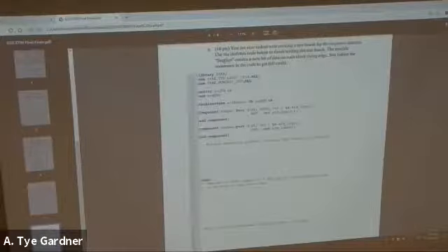Okay. So the first thing that it says to do is declare the necessary signals using as few signals as possible. What that's really looking to do is for you to build all of the clock, data, resets, detect signals, right? And the signals that connect those two together. Then you're going to generate a clock signal of 1 megahertz. You can do this through the process method that we've used before, or you can use the clock equals not clock method that I've shown as well.